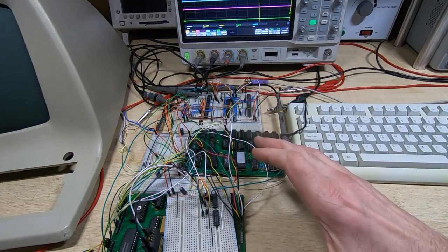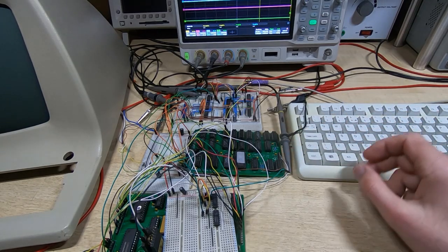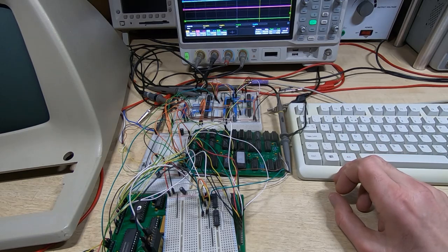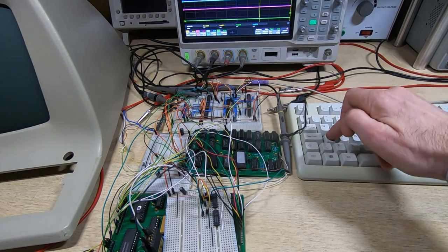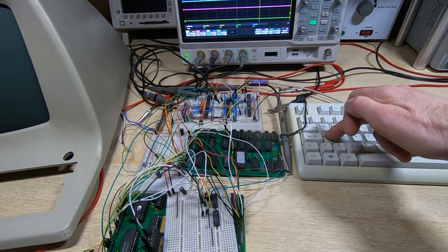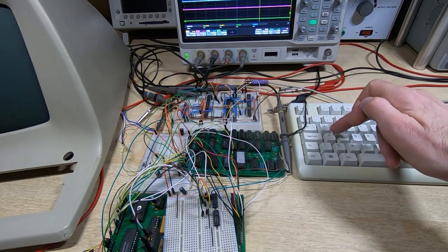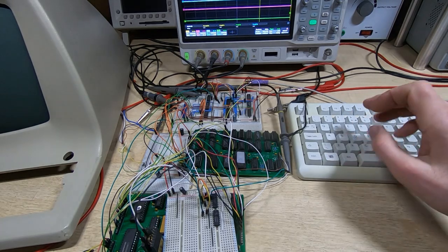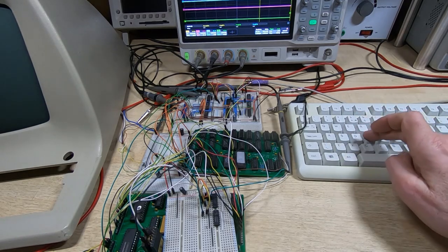But it wasn't interpreting the data into ASCII form, it was just printing it as the raw values that were coming through. And each time you press a key on a PS2 keyboard you will generally get more than one data packet being sent. So the keyboard will send a data packet when you first press the key down that relates to the particular key you're pressing. It will then send a specially coded data packet when you first release the key, and then it will send a repeat of the code for the particular key. So you'll generally get at least 3 data packets each time you press and release one of the keys.